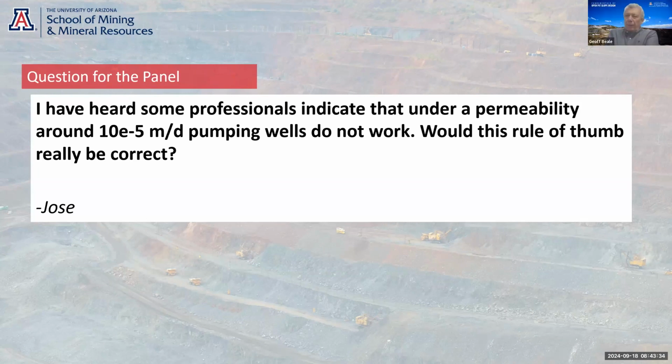Yeah, I mean, that's 100%. If you think about what fractured rock is, the rock matrix itself is probably 10 to the minus 10, 10 to the minus 11, 10 to the minus 12 meters per second. So you're never going to pump water out of solid rock, but the fractures may be 10 orders of magnitude higher than that. So in fractured rock, you've always got this massive permeability contrast. And you might have a 500 meter well where 499.9 meters of that well is 10 to the minus 12, and you might have one fracture which is 10 to the minus 2.